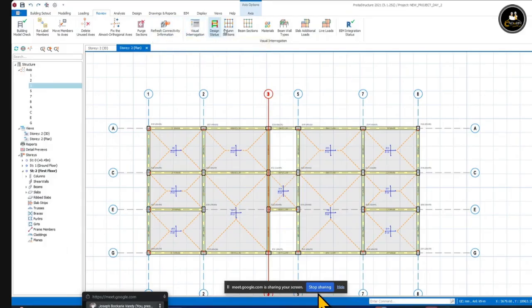No, no, no. Which one? Column section? Click. If you have different sizes of columns, you'll be able to see them here. You can see now that not all these columns are uniform. Maybe you intended to use uniform columns, but by mistake you used a column you didn't intend to. You can easily check them in column sections here.